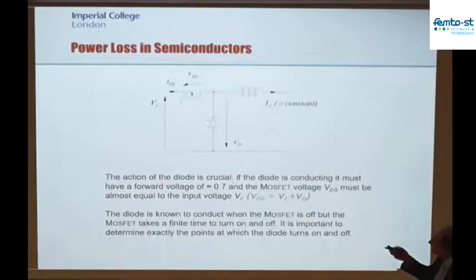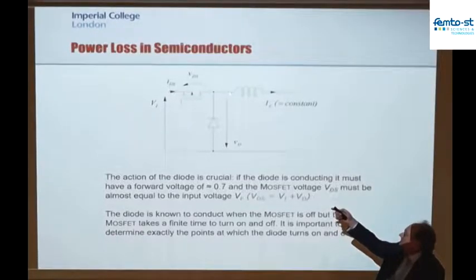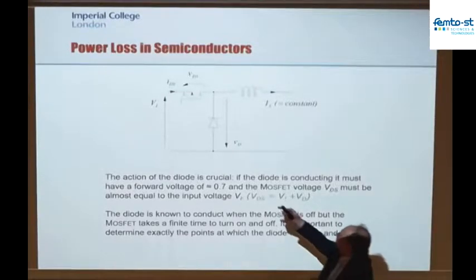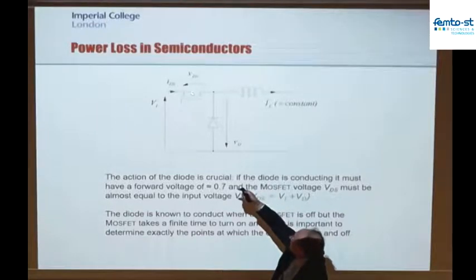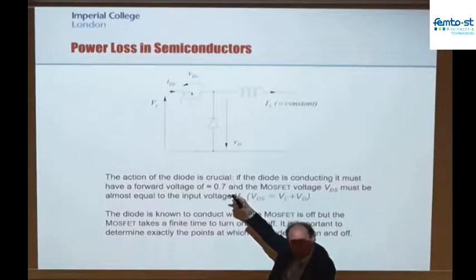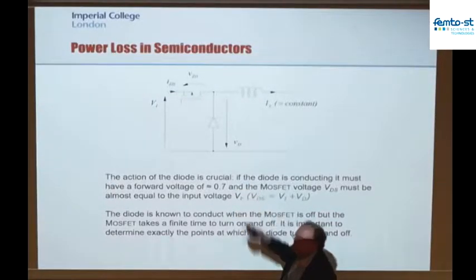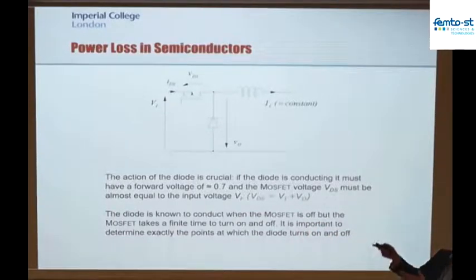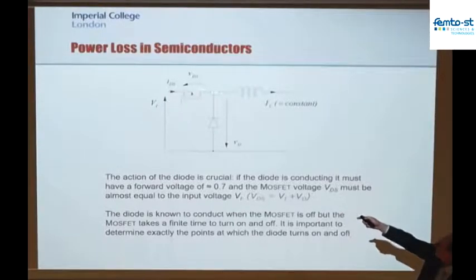And if the diode is able to conduct some current, what does that imply about the voltage at this node? It's got to go towards 0, hasn't it? In fact, it's got to go slightly below 0 to be able to turn this diode on. So before I can even start to move some of this inductor current out of this transistor into this diode, that voltage has to collapse. It has to go all the way to 0 and slightly below in order to pull that diode into conduction. And even before it reaches 0, if it's just slightly above 0, that diode is switched off. But now that transistor has actually got the full voltage V in all the way across it.